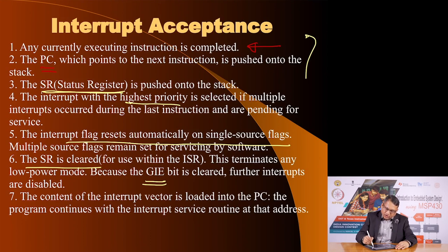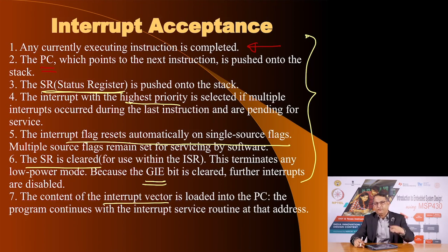Once these conditions are all met, then before you go into the subroutine, the interrupt vector is loaded onto the program counter, and from there the microcontroller starts fetching and executing the instructions of that subroutine.